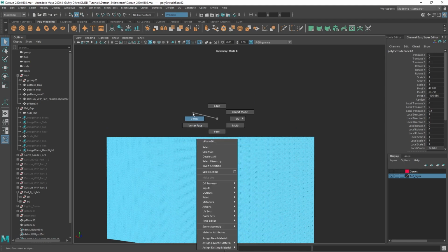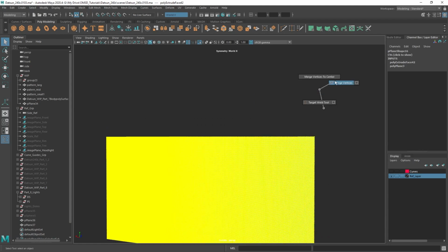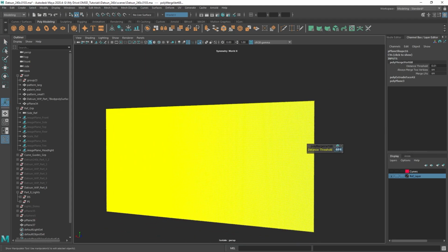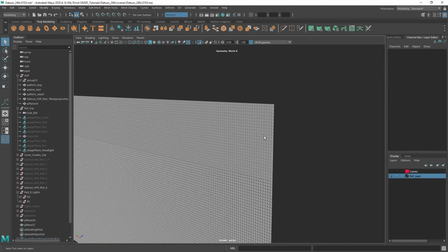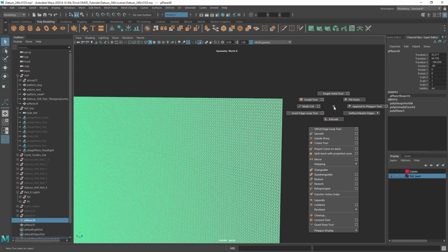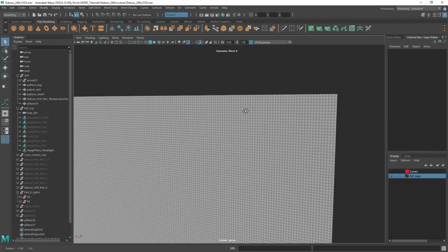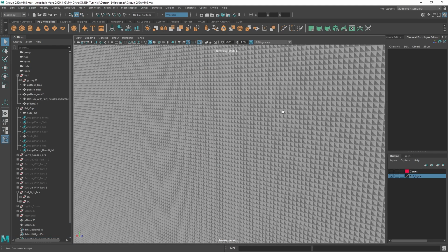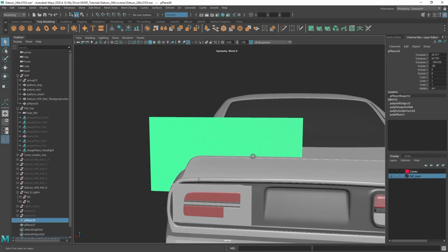Then I go ahead and grab these, merge vertices, and do these really small values, like 0.001, 0.003, and there you go, right? And again, I would do soften, harden edge, and you can just do a harden edge on this one, and look at that. You get that really, really nice pattern. Okay, and I then go through and cut and boolean all the same.